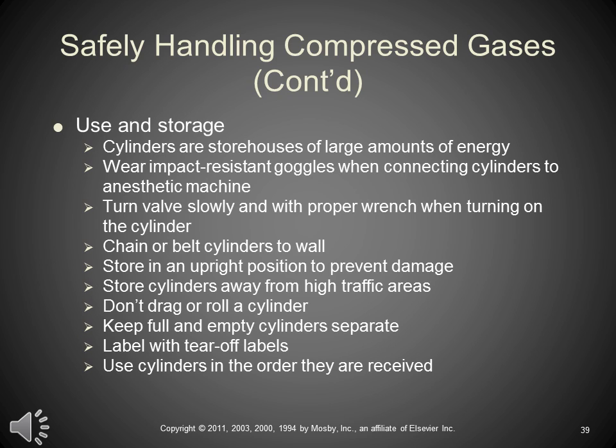Use and storage of cylinders. Cylinders are storehouses of large, sometimes almost unbelievable amounts of energy. You need to wear impact-resistant goggles when connecting cylinders to anesthetic machines. You need to turn valves slowly and use the proper wrench and tools when turning on the cylinder. You need to chain or belt these cylinders to the wall. Don't use duct tape like I've seen done before.